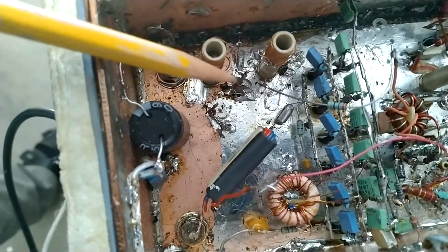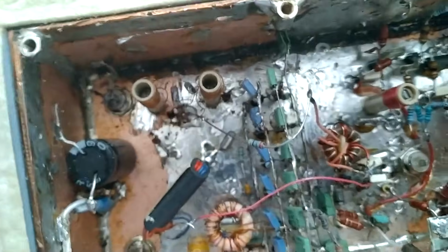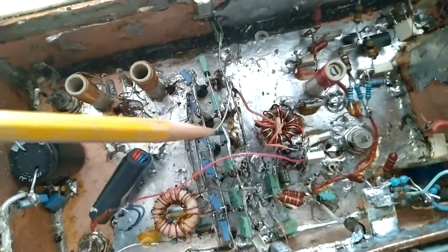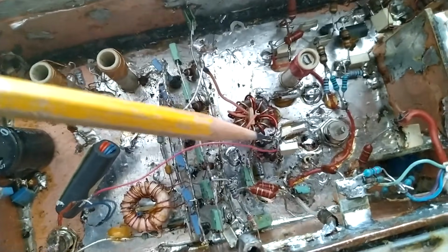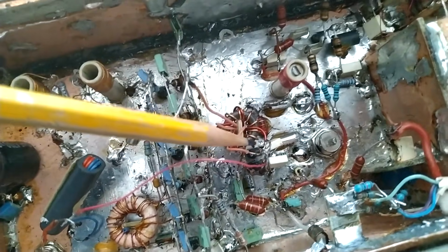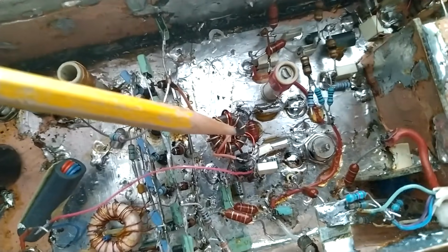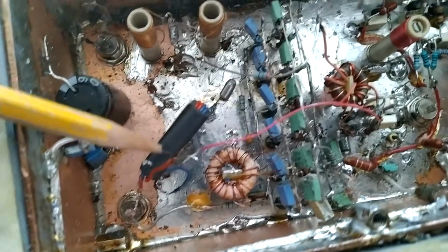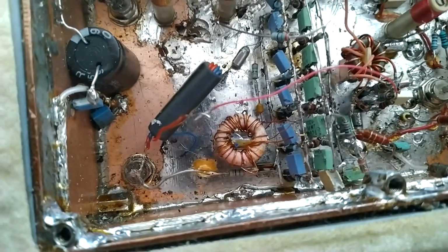And then I'm using the old limiter, which is 2 crossed diodes here between 2 series resonant links. And this is the old output amplifier, which I'm not using. I'm taking the signal directly from the amplifier stage that feeds the limiter, and then a transformer to not load it too much, just to measure the first steps.